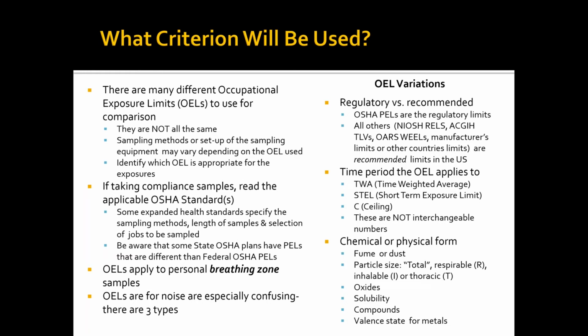Another really important thing that you'll hear me talk a lot about is the time period that the occupational exposure limit applies to. And this is really critical because this will really drive how long you sample and, indirectly, the flow rates that you might use.